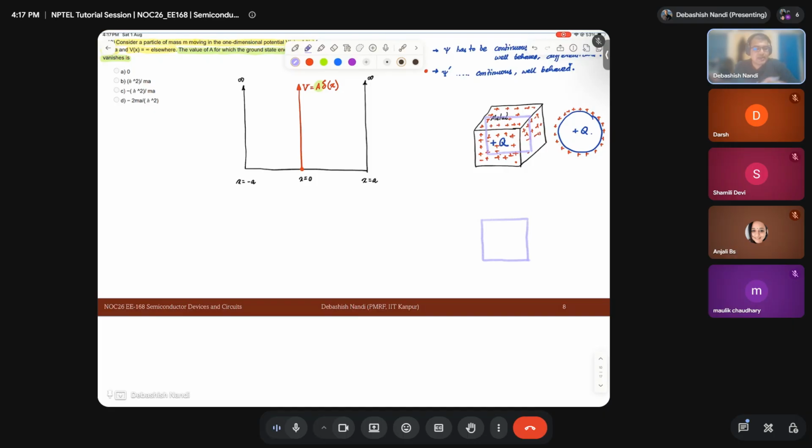So cover the apparatus with aluminum foil and then you are essentially isolating the internal experimental setup from the outer world, right? By doing Faraday caging, you are essentially prohibiting anything, even light. Light is also an electromagnetic wave, right? Light or any other currents passing through a conductor will not get coupled into your experiment.